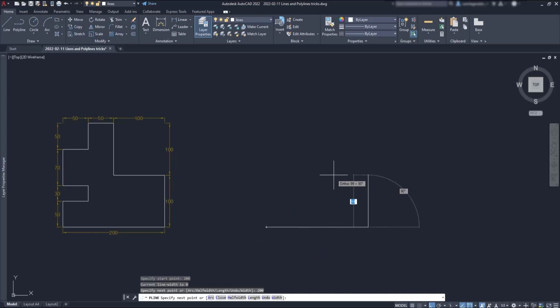Then I draw each line by typing the exact length with the keyboard. And to make things easier for you, you can just look at the left drawing as all the dimension lines are there. Also, notice as we are in ortho mode, all the lines snap vertically or horizontally, and in this way we can draw all the lines much faster. I'm going to speed up the process, and when I arrive at the last line, I'm going to finish the polyline normally by clicking at the endpoint.